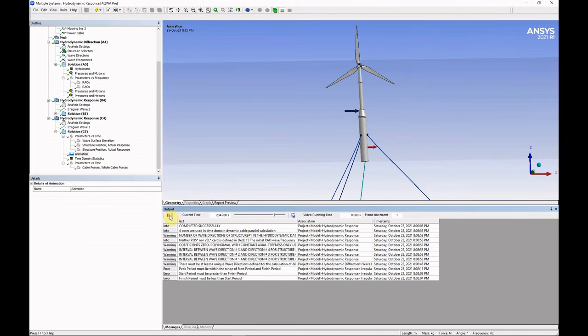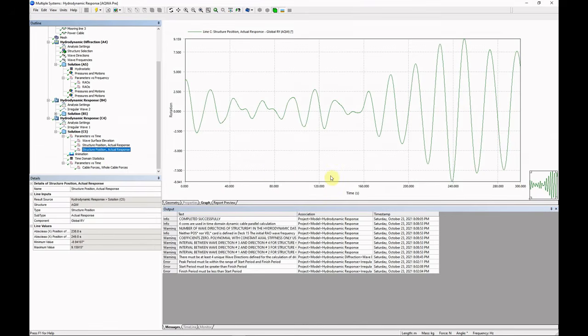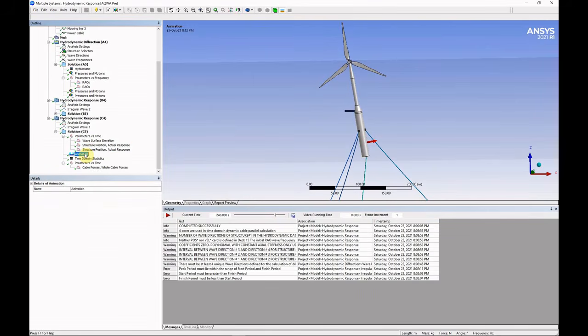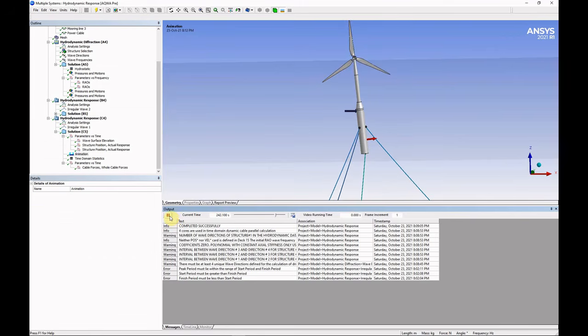We have started from a sketch, making realistic assumptions to design a spar hull and a typical wind turbine. We calculated the hull size and its static stability, and the mooring lines and a power cable property. Using this spreadsheet, we then made the structure's CAD model and set up the hydrodynamic diffraction system. Finally, we ran a time domain solution with a heavy storm wave height and period, at exactly the structure's resonance response, just for demonstration, but also a bit for fun.